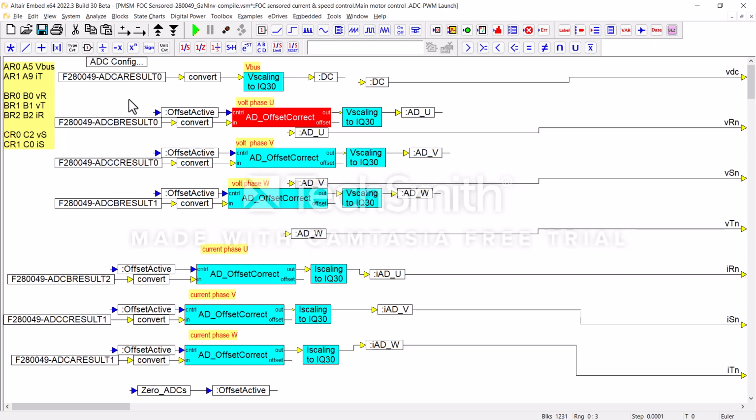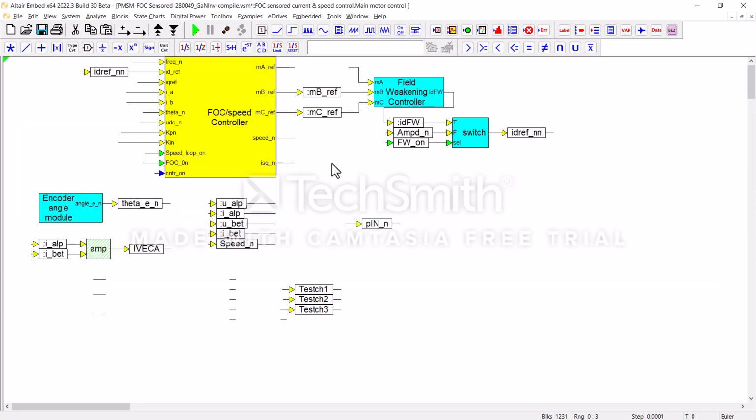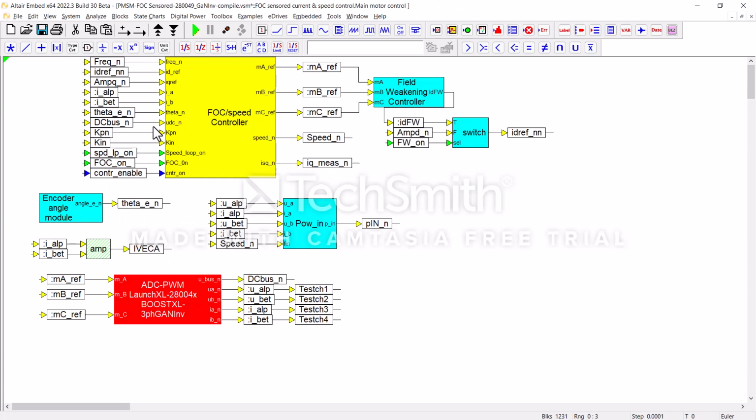So when the motor's running, if it's above that voltage, it is a positive current or voltage. Anything below would be a negative voltage or current. And as I mentioned, those are Clark transforms. So the alpha betas for the currents are fed into our current controller. The voltages we're just using for our power calculator. The voltages would be used for a sensorless controller, and that will be talked about in another session.